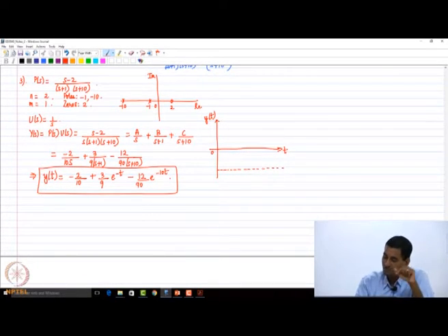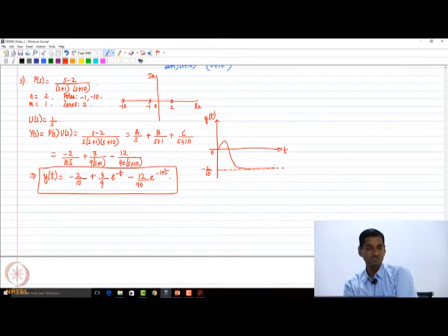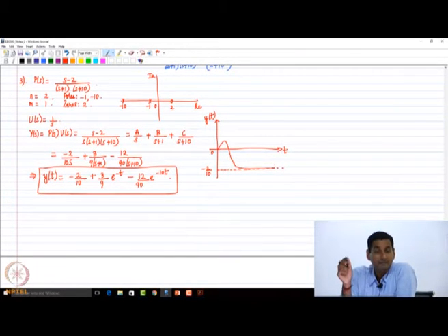You can go to MATLAB and plot this function. Let's say this is -2/10. So what's going to happen is that the output function will go something like this and settle down to -2/10. Okay, that's going to be the impact of the 0 at 2. Yes. Because as you change the 0 towards the right, it becomes more and more negative. Which one? The final value, yeah, it depends on how you write it.